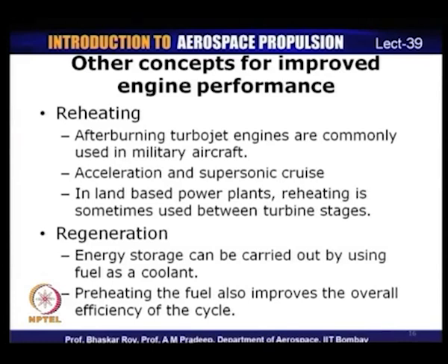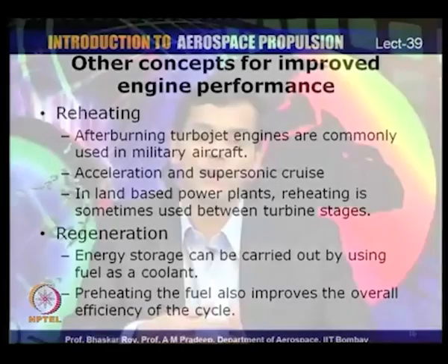The third aspect that one would like to use is regeneration, wherein energy storage can be done in the case of aircraft engine in the fuel, where fuel can be used as a coolant and you can preheat the fuel by cooling some of the other components, and therefore, regeneration in some form can be implemented by using fuel as a regenerating fluid. And so, these are some of the concepts which, like intercooling and regeneration, can probably find applications in future aircraft, besides the other concepts like what we discussed for supersonic transport and also for short takeoff, vertical landing and other such engines. So, these are some of the simple concepts that we might get to see in future air breathing propulsion systems, and there would be many more such concepts which will be discussed in the remainder of this lecture.